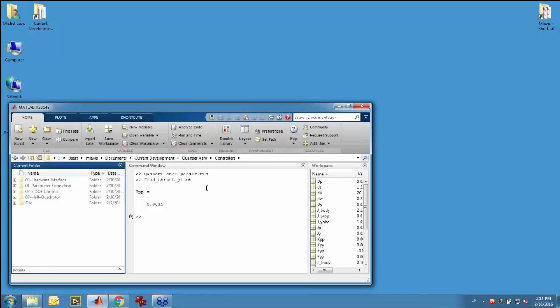As you can see, there's an Allen key that locks into place using these magnets. With this Allen key, I can choose to lock the yaw. If I put the Allen key in here, it fits through this, and then it locks into a little magnet here. You can't really see it on the camera, but in this little hub here, there's a magnet that couples to the Allen key that I've pressed down onto the unit. Now you can see that it's locked into the yaw. The yaw axis is totally locked, and I can conduct pitch-only exercises.